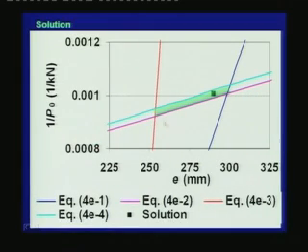When we zoom into that acceptable zone, we find that the four lines give a region which is shaded as green, and that is the acceptable zone for this particular section under the given load combinations. The selected values of E and P0 indeed lie within the acceptable zone.